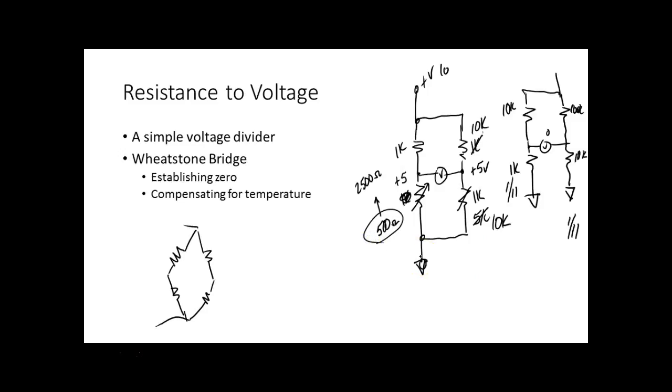You understand? But I know I've got it in a glass of ice water, and it's a temperature sensor, and it should be measuring 32 degrees, right? You understand that? So I could calculate my transfer function, and I would adjust this. So I'd say my maximum I would get out would be something. We'd figure that out when it was down at this minimum. I'd figure that out, and then I would get my transfer function, and then I could come up here and adjust this. Well, I wouldn't even need that. I would just start adjusting that. So I've got it in ice water, right? You understand? I don't even know what the minimum output of my thing is. I'll start adjusting it until it measures 0. Right?